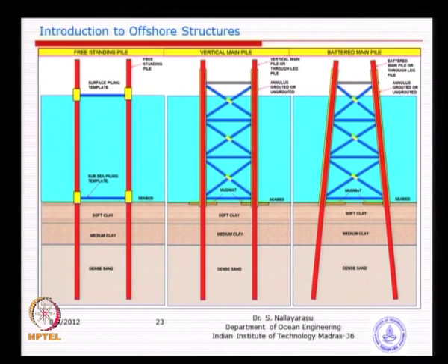In several cases, you see these 3 pictures, how people have been thinking: you have a template at the bottom and a template at the top, which controls the spacing. Then instead of that, because holding these 2 things together will become difficult, isn't it? How do you do it? Somebody has to hold the top and bottom without dislocation during pile driving. So in order to achieve that, you make a steel truss, just weld a few members. It becomes a simple template with which anybody can happily drive the pile. And you see the last one is just a manipulation of this to reduce the pile load, because I wanted the base to be bigger. I think it is a simple idea transferred from one concept to another.